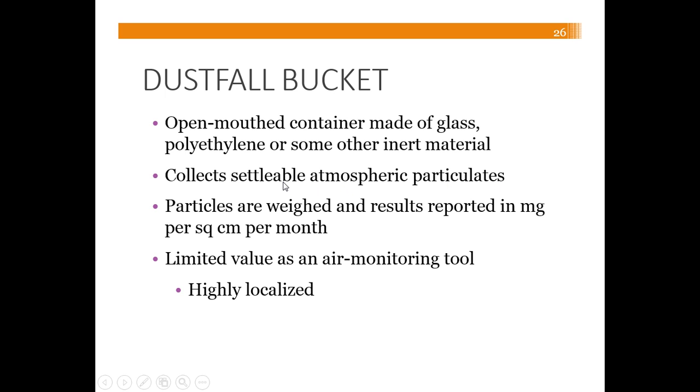So you're talking about really the coarser, heavier material that would drop as a result of the weight of gravity. What is collected is therefore weighed, and results would be reported in milligrams per square centimeter over a month's period. So you'd be looking at each month how much settleable particulate material was acquired.